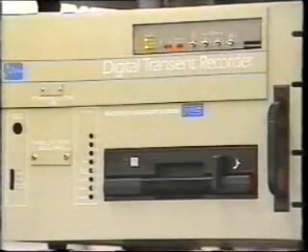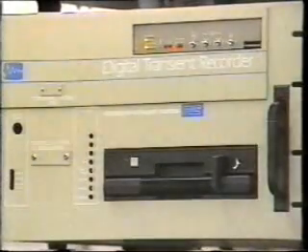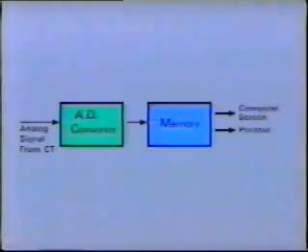In recent years, most of the fault analysis systems installed are of the digital type, generally known as digital fault recorders. This type of system usually allows for a greater number of monitoring inputs. The measurement, that is, sampling, is made simultaneously from all inputs, and a very high rate of sampling is achieved, say 6,000 measurements per second. The analog input is converted through an AD converter into a digital signal to be recorded in the memory of the recorder. The information can be viewed on the computer screen or printed out as required.